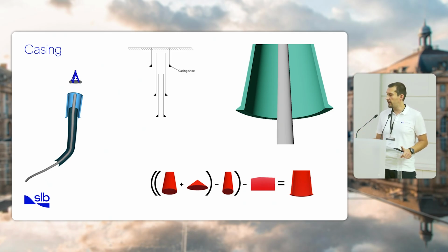We can even add an optional clip plane, which is parallel to the camera plane, to see the inside of the tube. And we have the final shape, which is, again, infinite resolution, infinite quality, and perfectly smooth, and which is direct recast, which means there is no marching loop, so no magical epsilon number or magical maximum step. This is direct recasting.